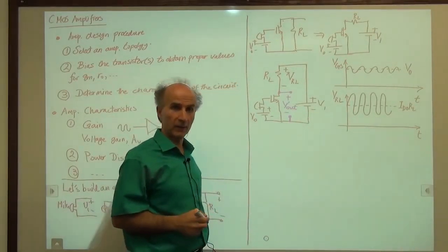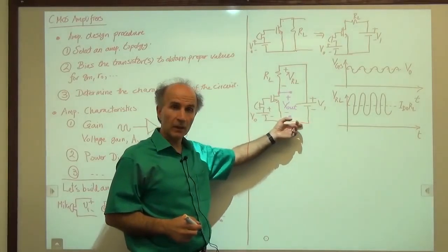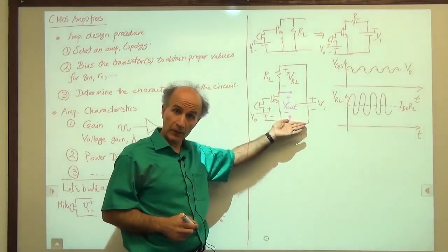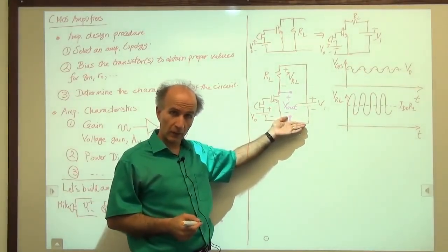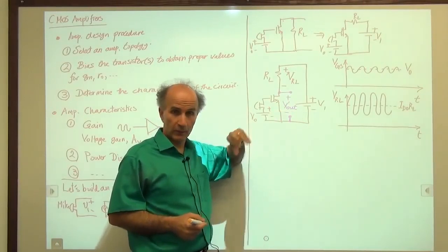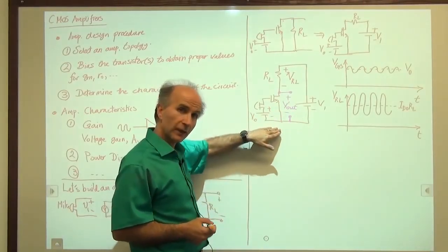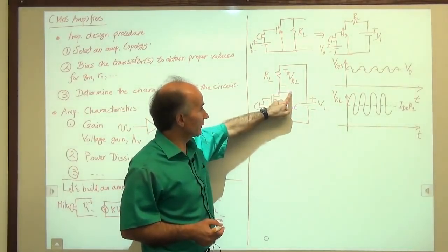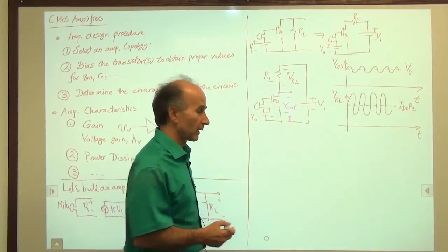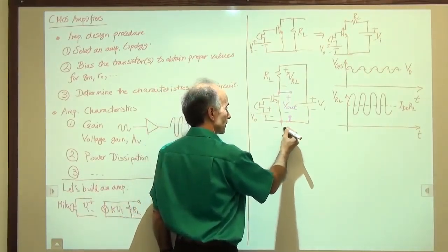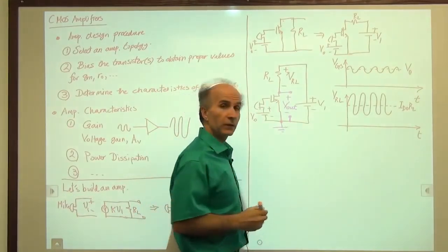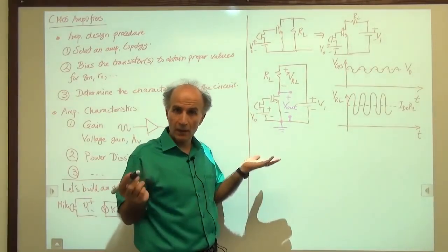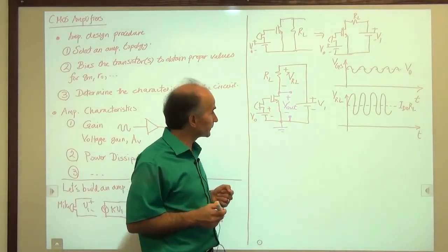Okay, we prefer that. You see that this is sort of a common terminal to all of these, a common rail, we call it, or a reference point, if you remember from circuit theory courses, or a ground, as you might remember from those courses, right? So we call this ground. It's common to all of these. And we prefer to measure the voltage at the drain with respect to this ground. Let me put a symbol of ground here. This might be familiar to you. So that's called the ground. This doesn't mean that it's necessarily connected to ground. It's just a notation to simplify things.